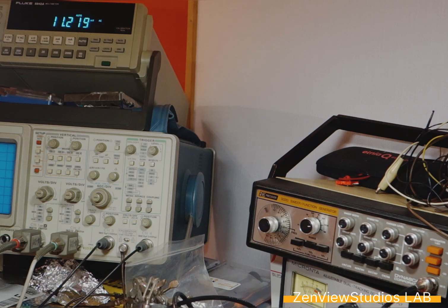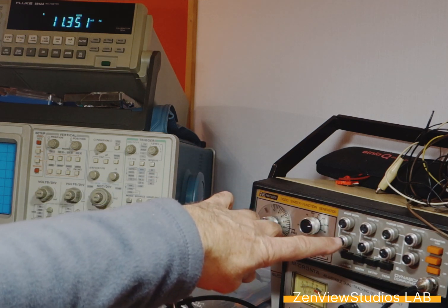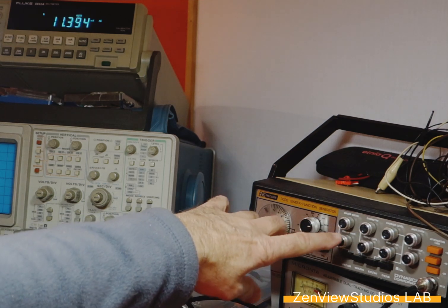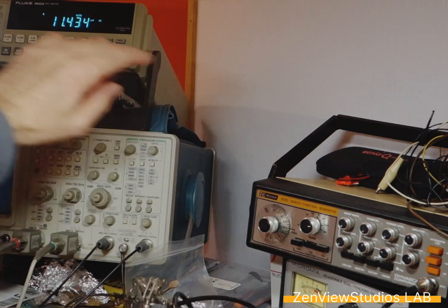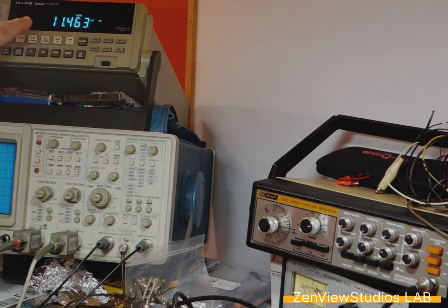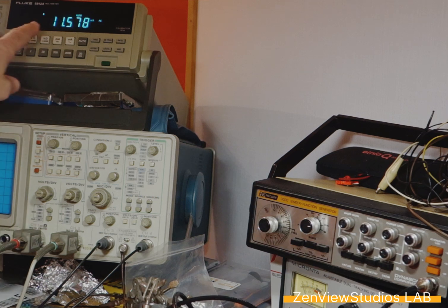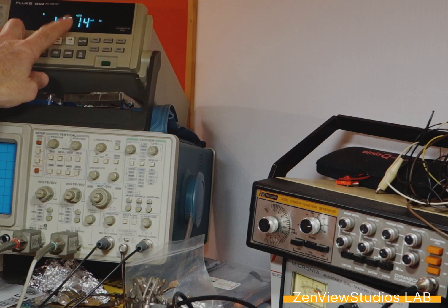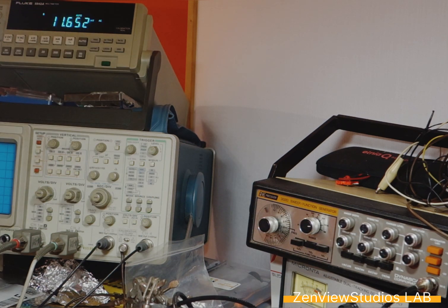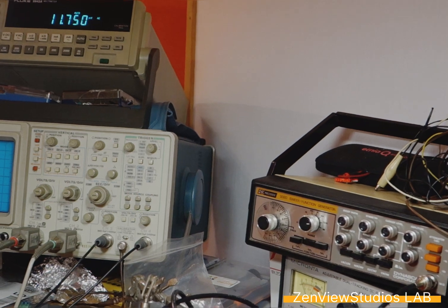That's what it reads exactly. The calculation is fairly simple because you have 50 ohm here, 500 millivolts RMS, and it's down to 11 millivolts here. If you run that by the voltage divider that it's making, you get that this reads really 1.16 ohm. So pretty close to that 1.18 or something that we read with the ESR meter.